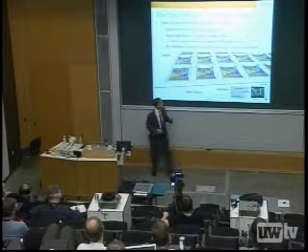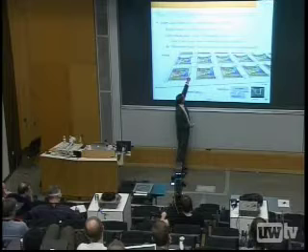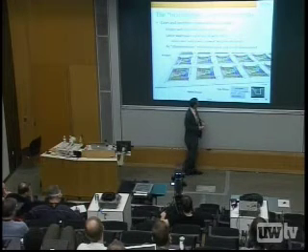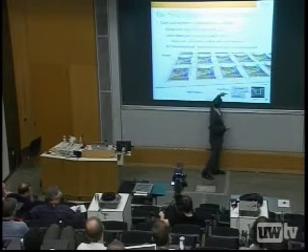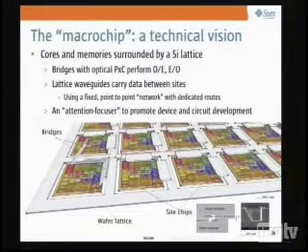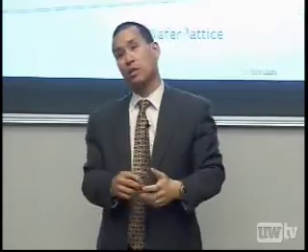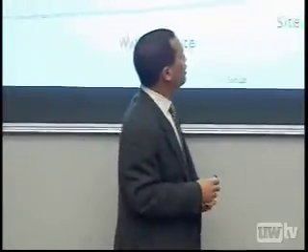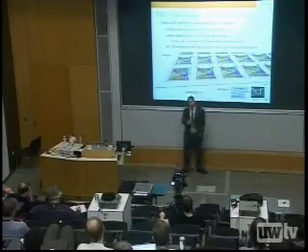Now to do this, of course, I need to make sure that I can get waveguides on this bridge chip to match up with waveguides on the lattice chip. We showed that at Group 4 Photonics, where we took a waveguide on one chip, for example, on this top chip, which is a bridge chip facing down. The waveguide terminates into an etched facet of the 111 silicon plane. That's 54.7 degrees. If you silver it, it becomes a mirror. So light hits this, bounces off, hits a matching mirror on the other substrate, boom, goes into a waveguide. We've got chip-to-chip communication optically. That's optical proximity I/O. We've shown that's about a dB of loss per chip, so it's relatively reasonable.